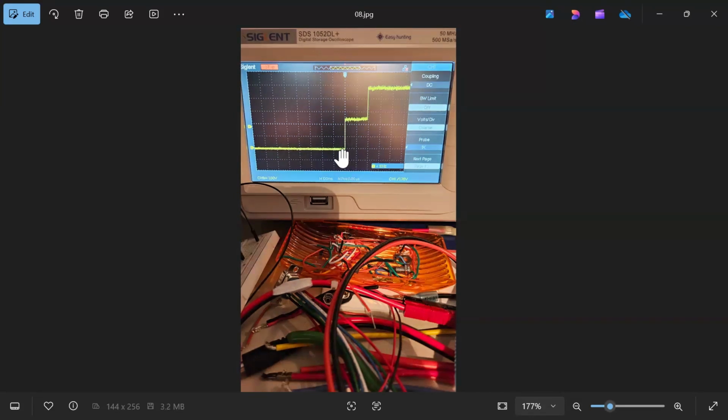The circuit is powered up. It comes up at the 50% power level, and after the 200 milliseconds, the PIC turns on the MOSFET, which bypasses the power transistor and outputs our full power to TTL computer 2.